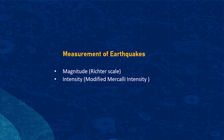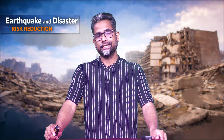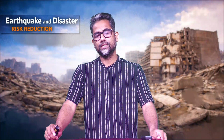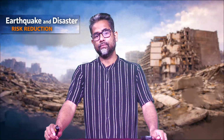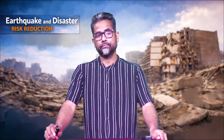Earthquakes are measured in two main ways. First, magnitude: the total energy released at the source, measured on the Richter scale, which is a logarithmic scale. Each whole number increase means approximately 31 times more energy. For example, magnitude 7 is 31 times stronger than magnitude 6. Modern seismology also uses the moment magnitude scale, that is, the Mw scale, which is more accurate for large earthquakes and is now the standard in scientific reporting.